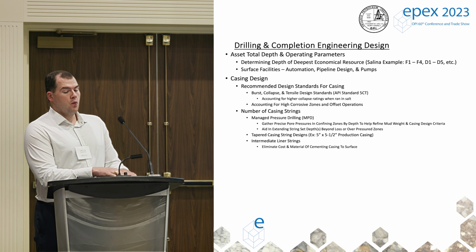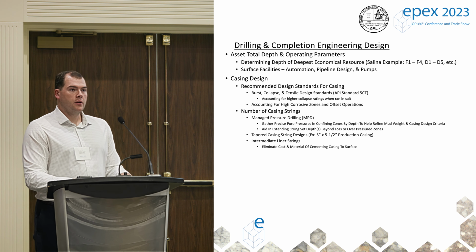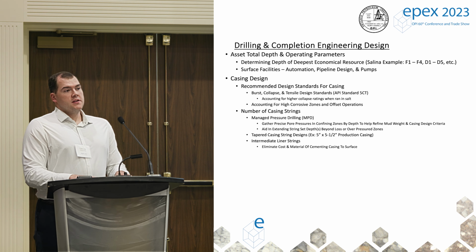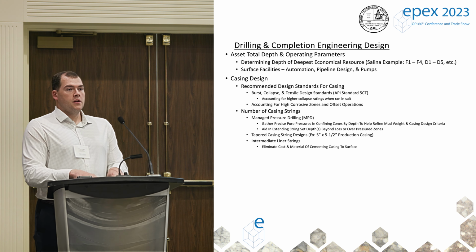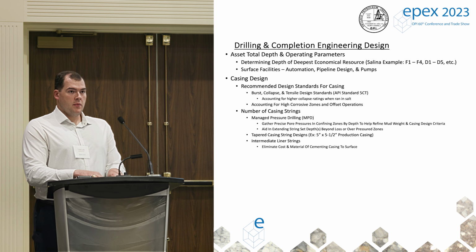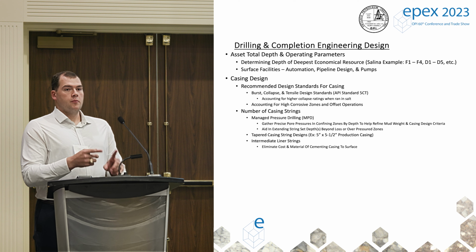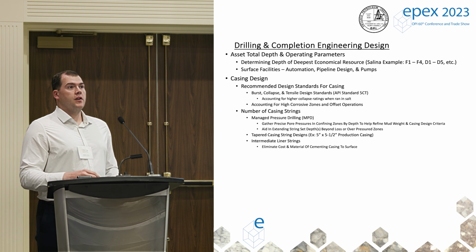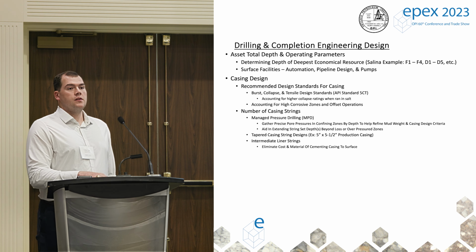After that, being realistic about data up front, I know there's not as much development opportunity. You're typically doing one-off, two-off, maybe multi-well or multi-pad drills occasionally. But I would really push operators to say, hey, figure out your pore pressure on the initial well, or initial couple wells. Spend the money a few times to figure out your pore pressure. That way you can optimize your casing design and operating pressures, and have a better understanding of potentially which way this salt's going to mine.